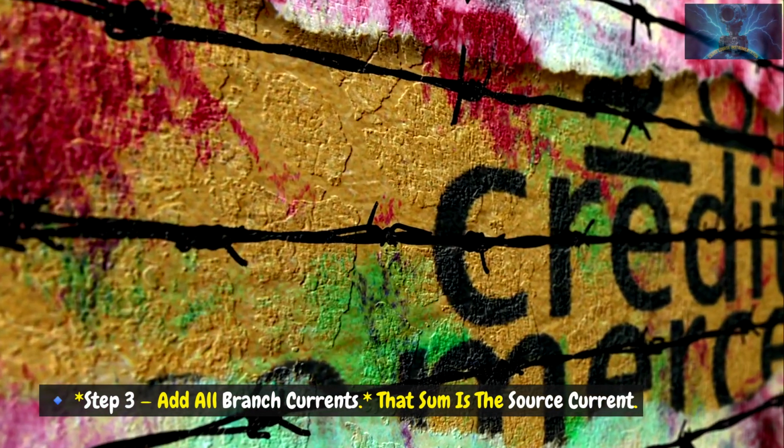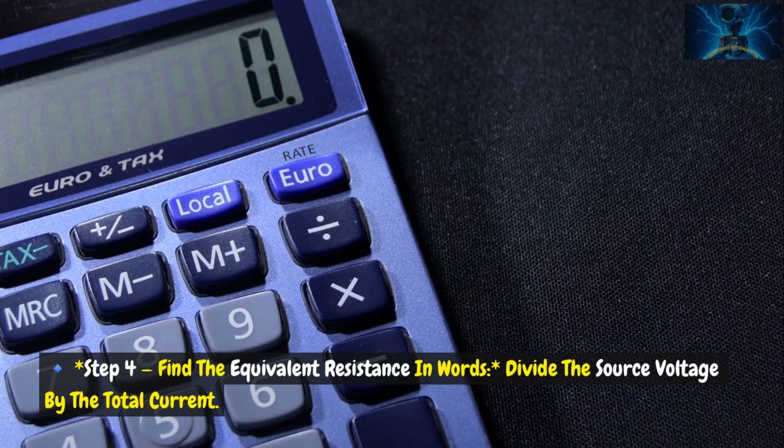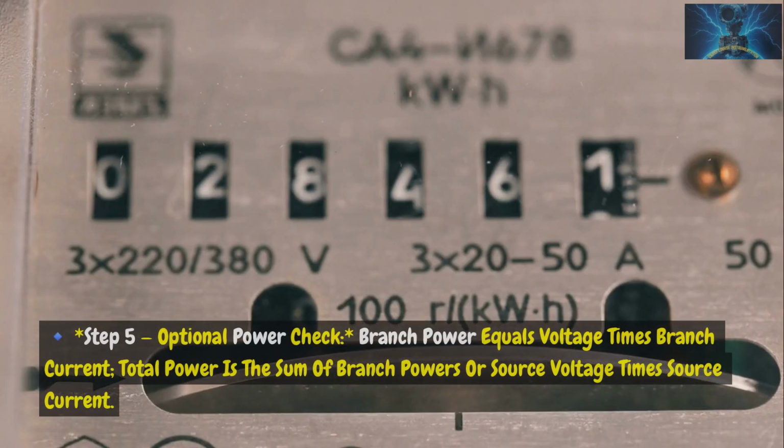Step 3. Add all branch currents. That sum is the source current. Step 4. Find the equivalent resistance in words. Divide the source voltage by the total current. Step 5. Optional power check. Branch power equals voltage times branch current. Total power is the sum of branch powers or source voltage times source current.